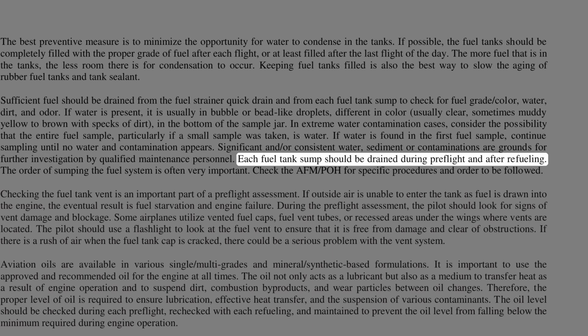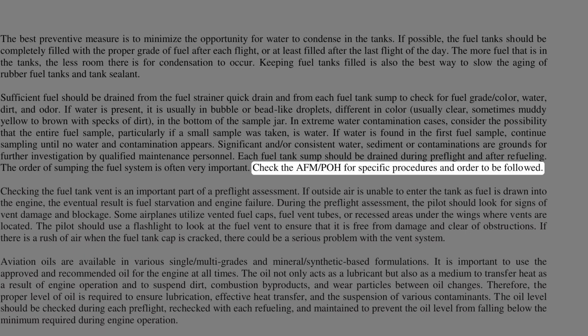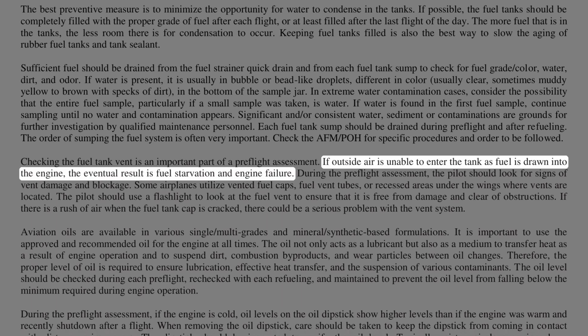Each fuel tank sump should be drained during pre-flight and after refueling. The order of sumping the fuel system is often very important. Check the AFM/POH for specific procedures to be followed. Checking the fuel tank vent is an important part of a pre-flight assessment. If outside air is unable to enter the tank as fuel is drawn into the engine, the eventual result is fuel starvation and engine failure.